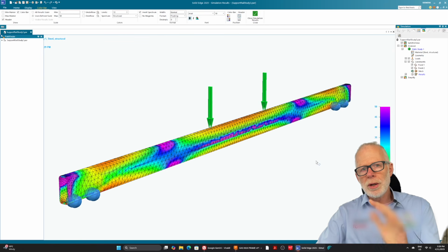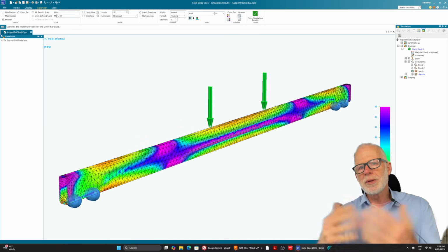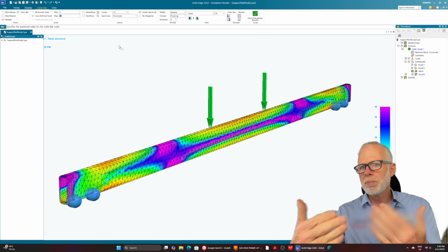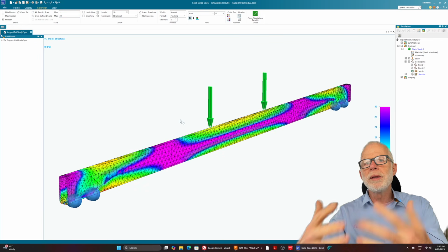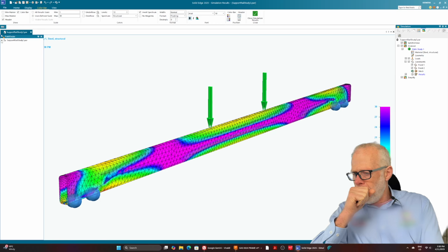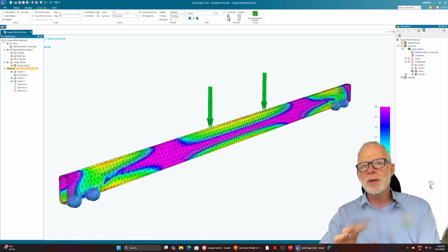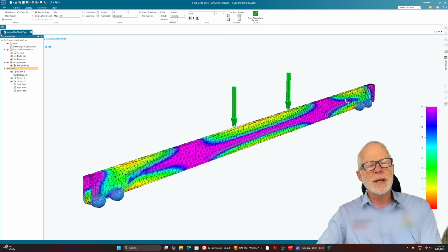You have to get the units right, you have to change the range of colours in the display, and you need to look for insights. Sometimes you're actually doing a section plane and cutting through the coloured results. And you're thinking about those questions that you had in mind when you first set up the simulation and started working on it.